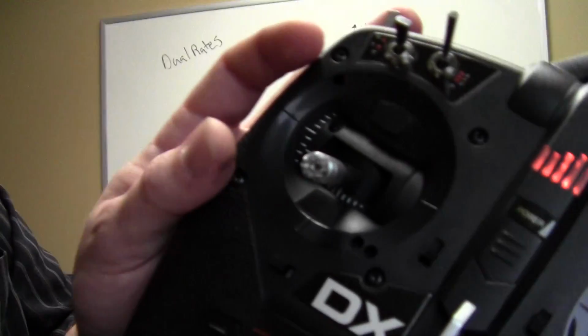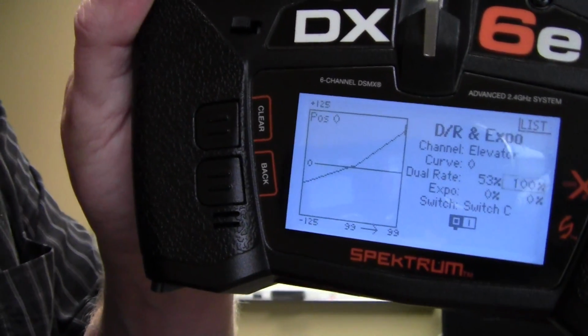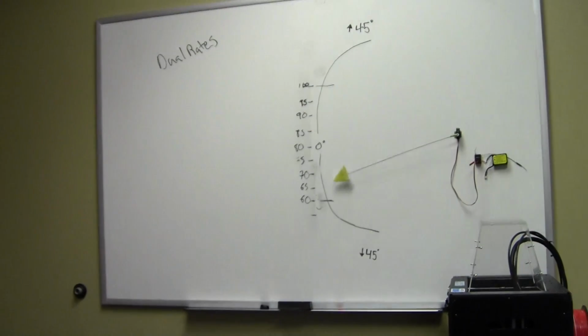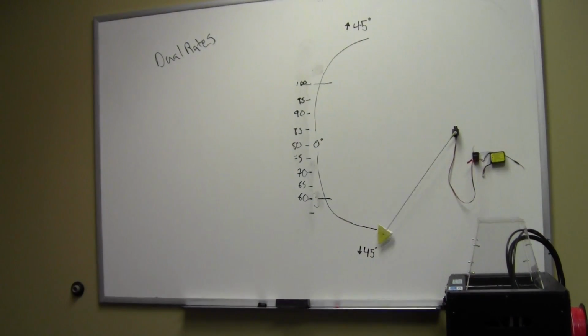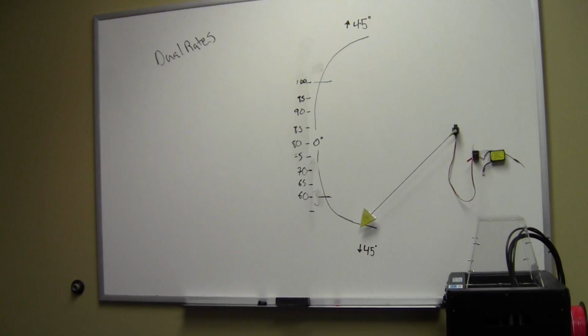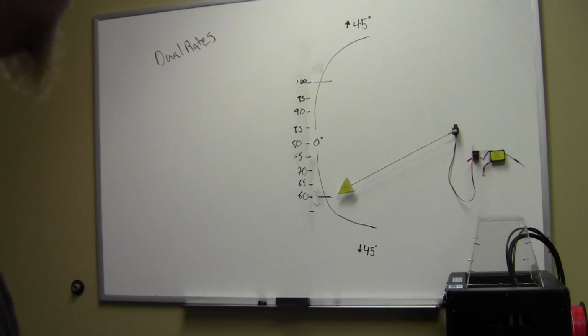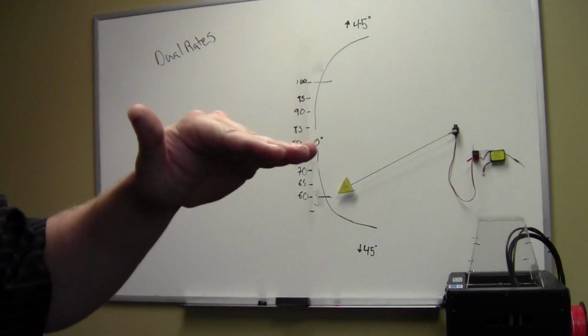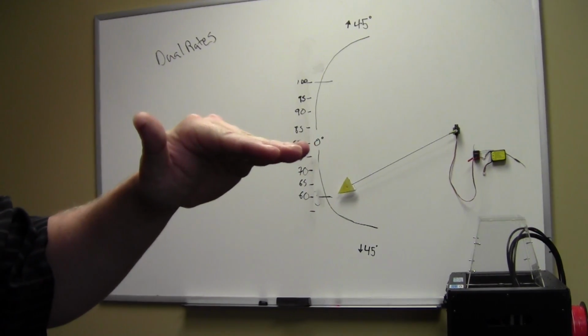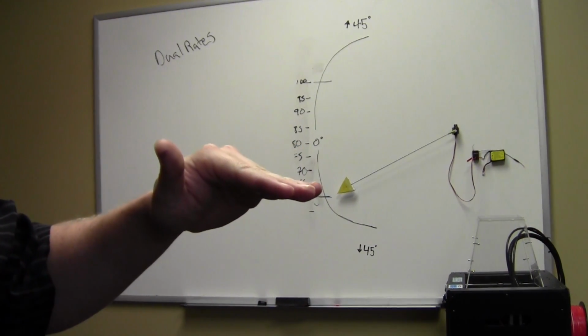And then same thing for down. We'll hold down elevator. It'll put a box around that. And we'll go down until our surface lines up with -20 or down 20 from 80. That's what we set there because we're pretending that our ruler is in the middle, right? So our ruler in the middle would be 80. We go down to 60.